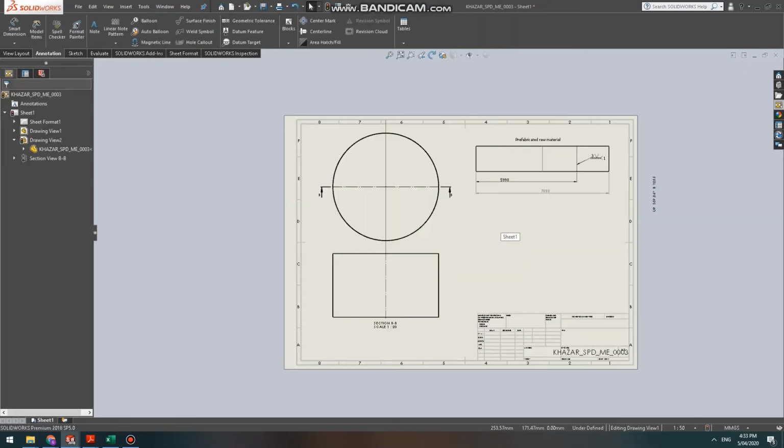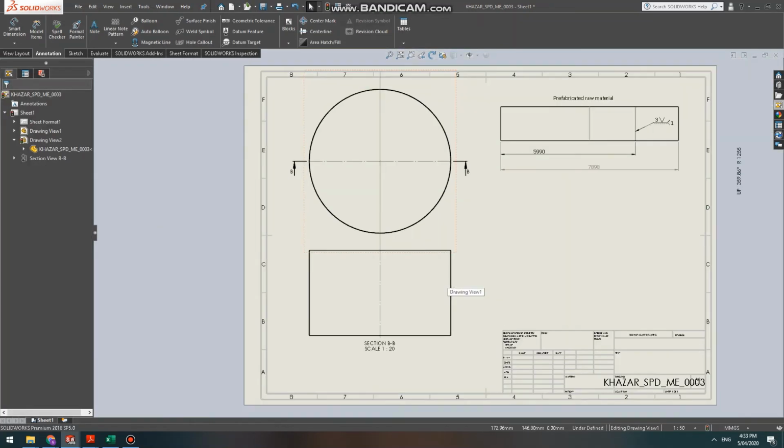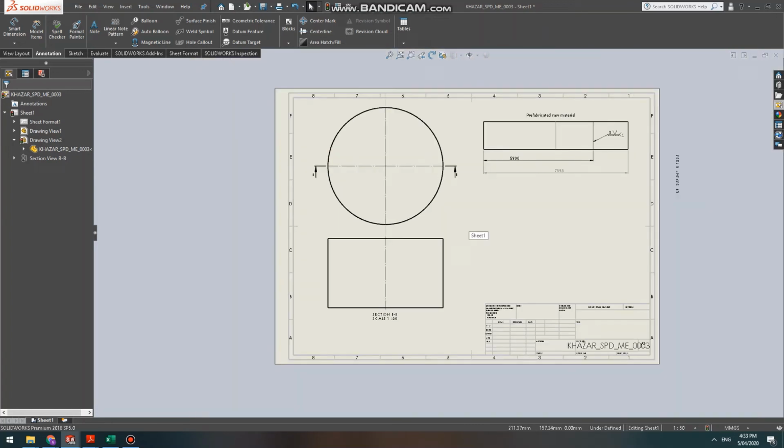And after you put them, you also need to show the bevels you did. So this 2D sketch is the sketch which will be received by the production side, by the shop floor, and people will do operations depending on the sketch.